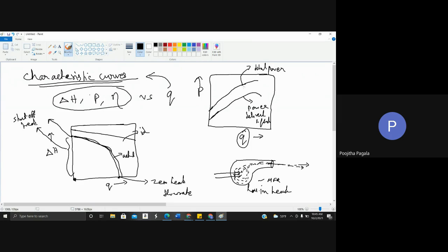So what is the difference between these two? The difference between these two is the power which is lost in overcoming this circulation and friction. So if you are inputting 100 kilowatts of power, let us say 20 kilowatts were lost because of this friction and circulatory flow, the remaining power is going to be just 80 kilowatts. So these two curves represent that.